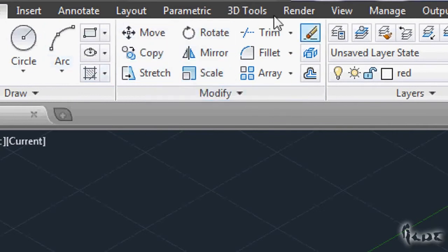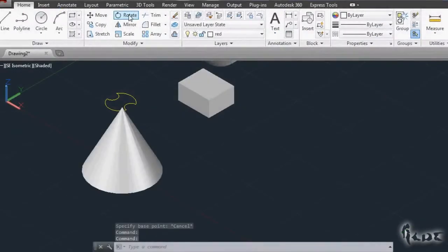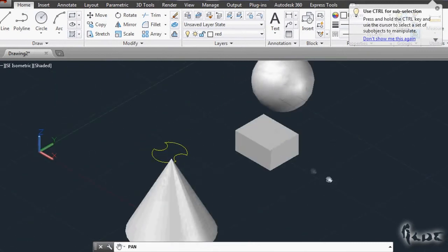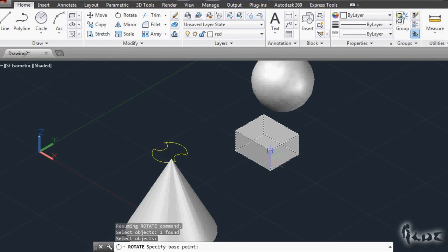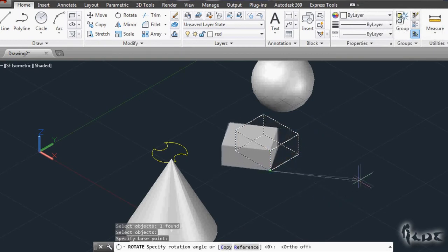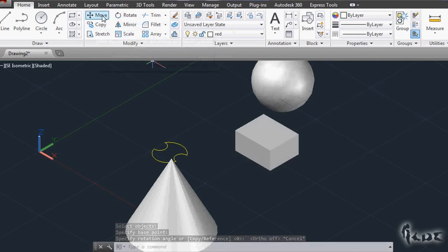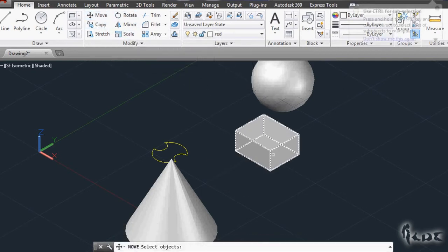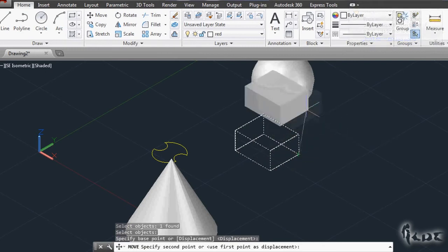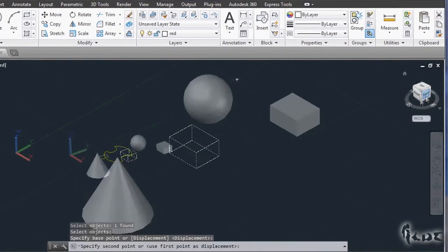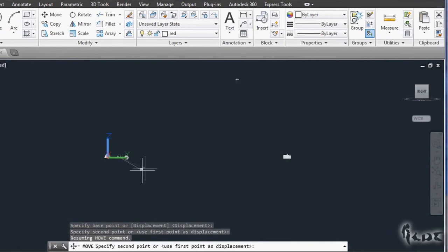You can edit your 3D objects further using the Modify section in the Home window, the same one you used for 2D shapes. But mind that some of these do act just through the XY 2D space, like the Rotate command. Some others do work fully in all the 3 directions. For example, Move lets you move in 2 directions always, but such directions do depend on the point of view used.